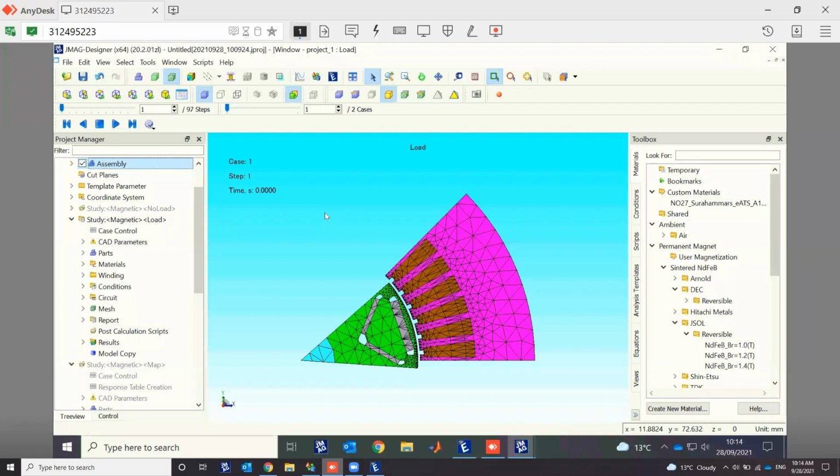torque ripple. So obviously in Express itself, you don't have access to too much customization, because we don't want to confuse, for the moment, the user that has no knowledge about FEA with too much detail. But actually, once you have created your model and you want to have a more detailed calculation and more access, as Ahmed showed, you can very quickly go into Designer, and then afterward you're free to continue in Designer to do your calculations. But in Express, we try to keep the number of variables that the users change to a minimum, to make their life a bit easier.